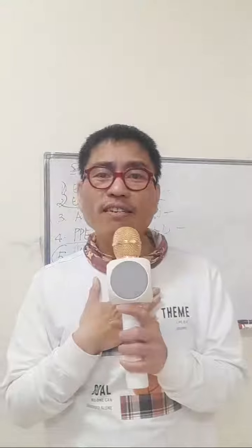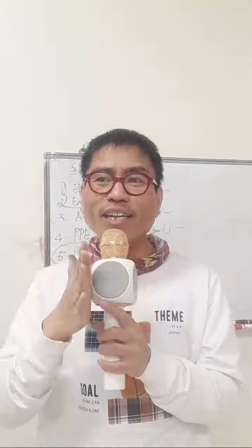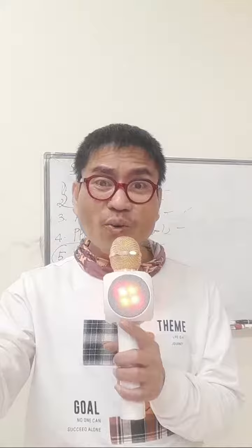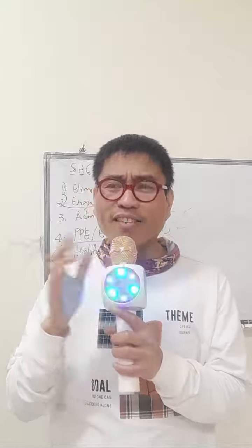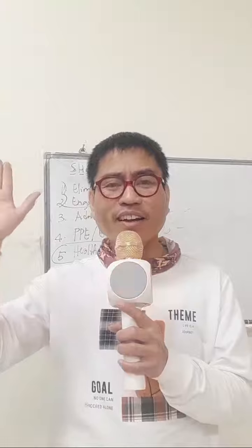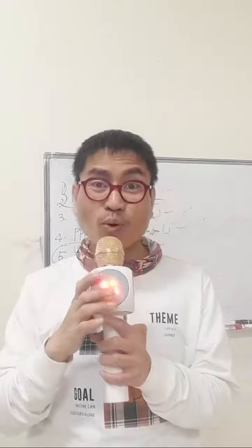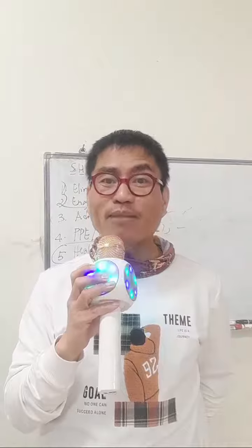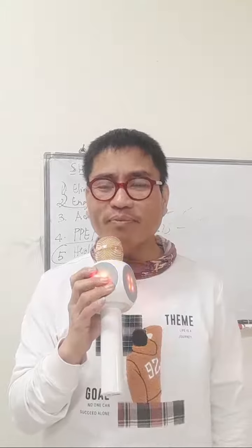What else? For the workers, for example, reading of chemical labels. You need to have an idea in reading the labels on all the chemicals. For example, you need to read the hazard signs and warning signs, whether it is flammable, hazardous, toxic, or reactive. Hazard statements are the words, and then the symbols. So that is the administrative control. You also have to have proper storage of your chemical containers, a good and safe storage area for your chemicals, and it must be properly labeled and identified. Get the point?